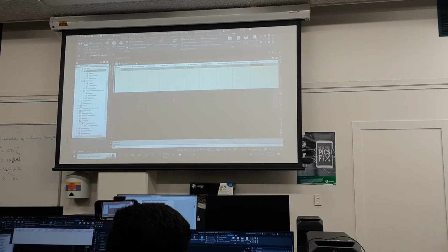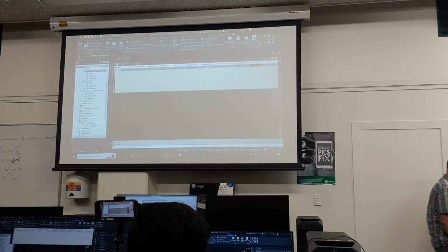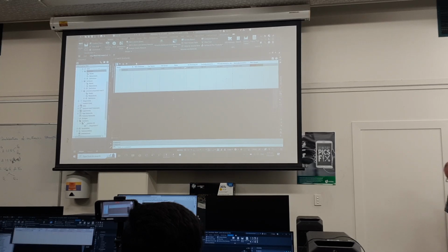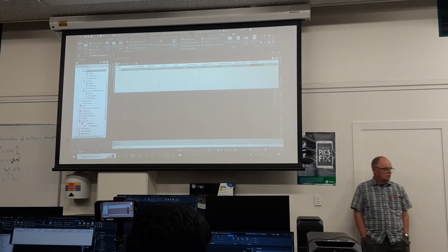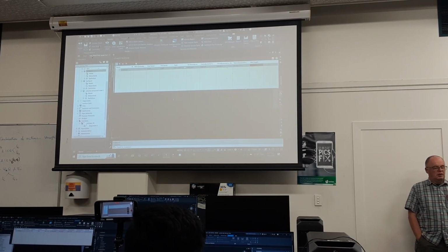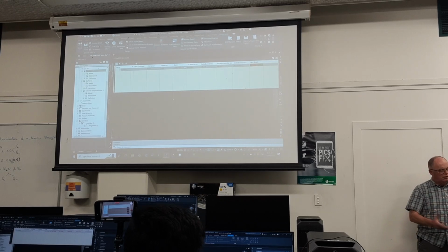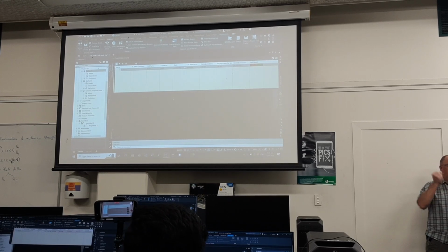So after you've done your design on Civil 3D, they often do some more numbers to work out what the real balance actually is. But all you can do is get it as close as possible. And then in the field, things happen and things are different as well. But just remember, when you dig soil out of a hole, you end up with a pile bigger than what can go back in the hole. And if you compact the soil in the hole, you need more soil to fill it up.